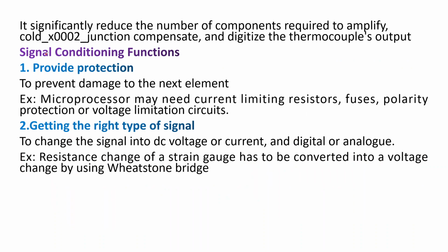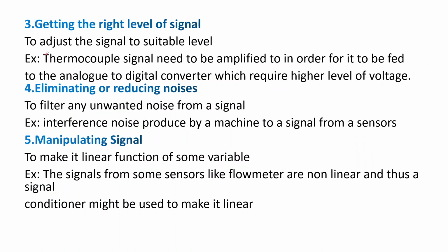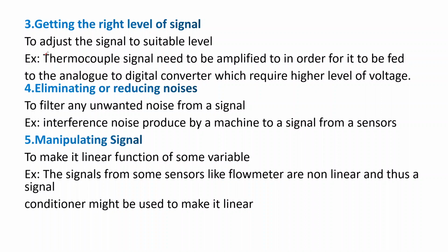Also, because of this signal conditioning, it provides protection. It avoids damage because of current limiting and fuses and polarity protection. Everything is limited, and it helps to get the right type of signals and the right level of signals, and it eliminates or reduces the noise level, and it manipulates the signals. So this is how signal conditioning of the thermocouple helps to produce the signal for the next level.